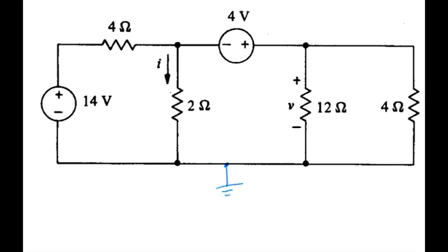So I'm going to go ahead and leave it attached on the bottom, and the two node voltages we have to find are V1 and V2. This voltage is already 14. So let's go ahead and do this at node 1. The current going off to the west, V1 minus 14 over 4, our southbound current.